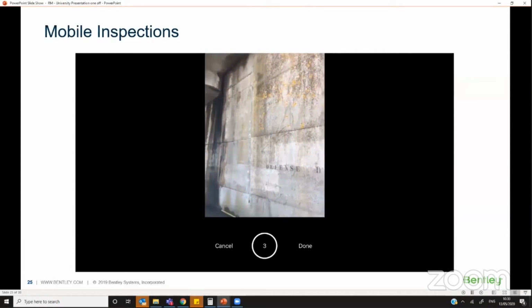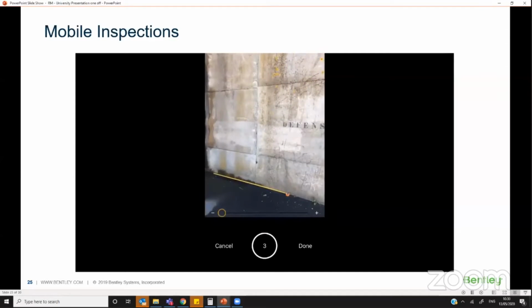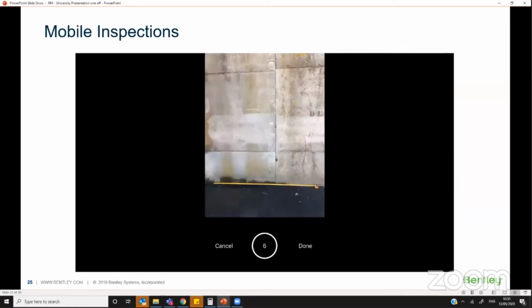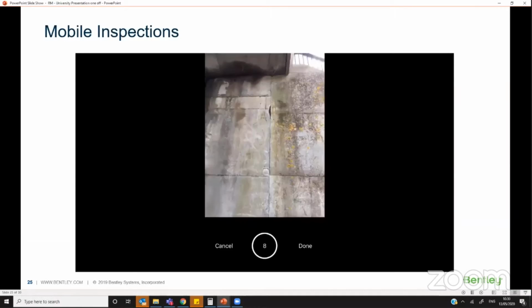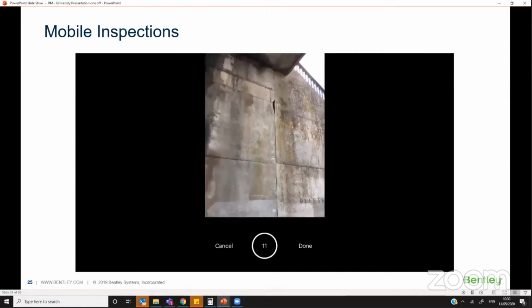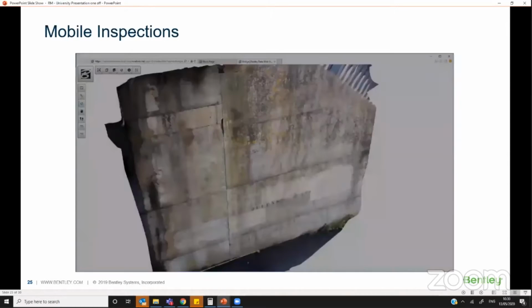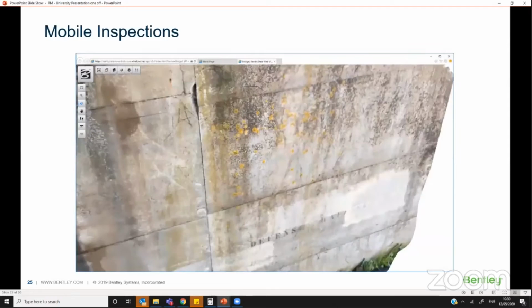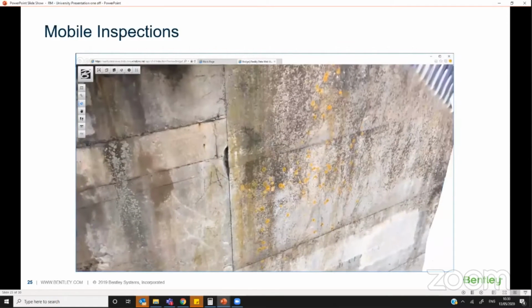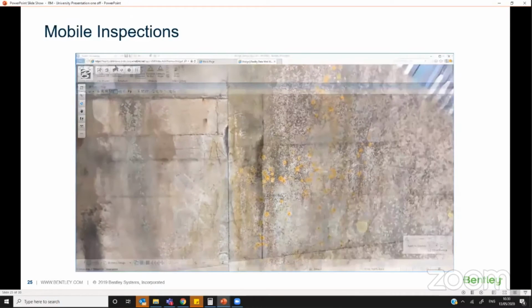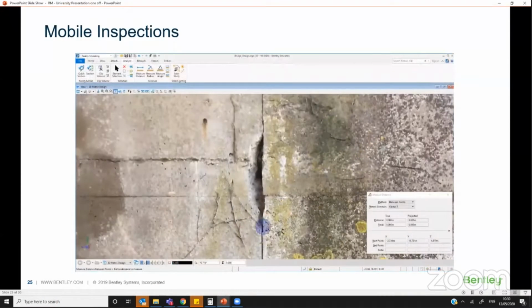He goes and takes some images underneath the bridge. He wants to concentrate on the actual defect, the crack underneath. He loads these photos into ContextCapture, and then as you can see, he'd walk away, turn his mobile off if he wanted to, and someone in the office would get the link. Once that link's in, they then take it straight into ContextCapture, into Bentley Descartes.